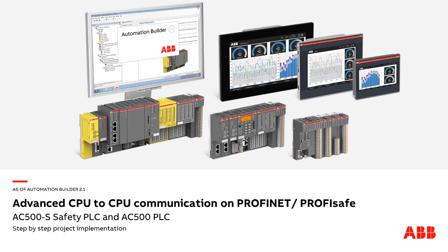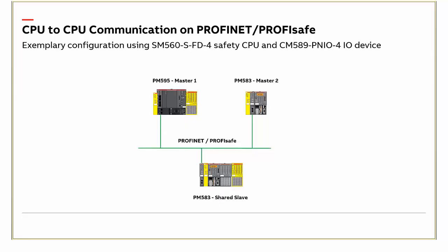I'm going to show you how CPU to CPU communication can be configured on PROFINET PROFIsafe using Automation Builder version 2.1. In this example, we'll show you configuration with two master systems, which are connected to one so-called shared slave. You can see this in this overview.